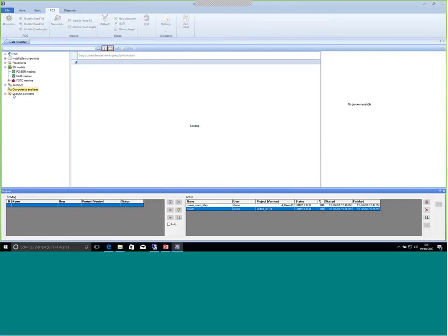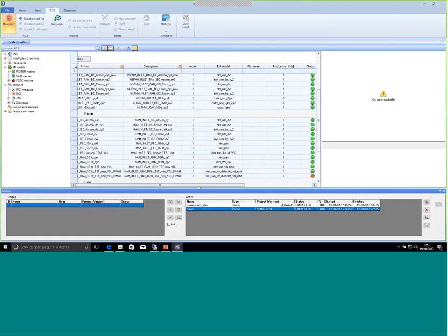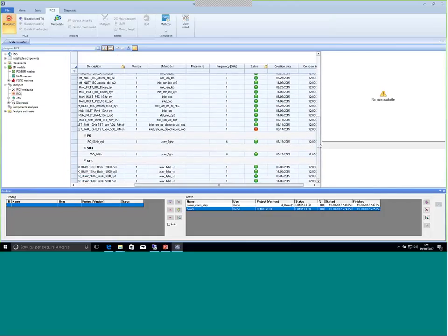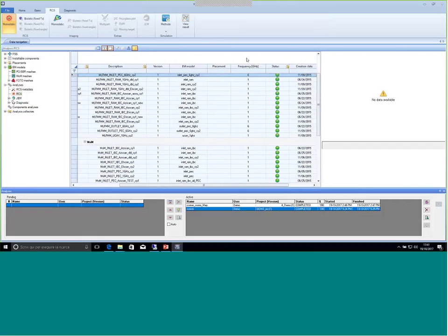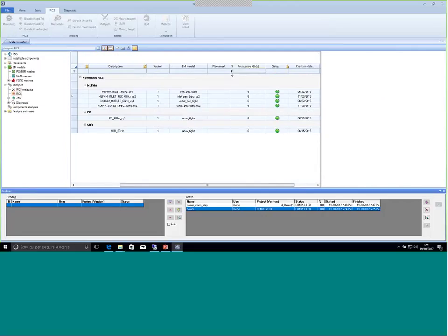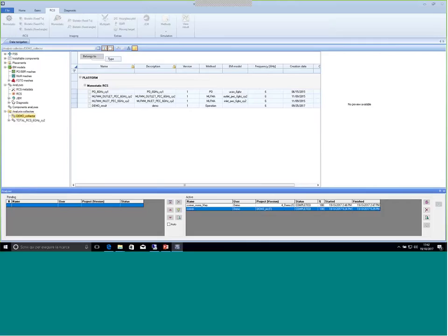Then I have simulated all these structures here, and I have done that at 6 gigahertz. For example, you can see that now I have quite a big amount of data, so it's not that easy for me retrieving this data, but I know that I carried out this simulation at 6 gigahertz, so I can just filter by frequency. So I can consider this result here and also the SBR that I have computed, and I can define a collector. In this collector, I put the PO analysis for the fuselage, the multi-level fast multipole method simulation for the outlet and for the inlet.